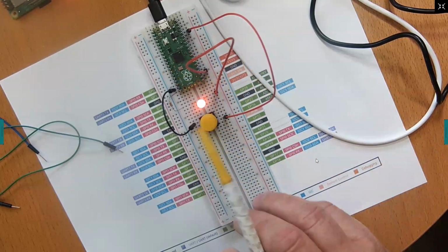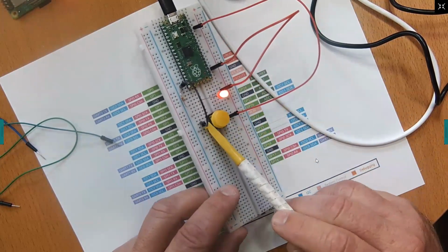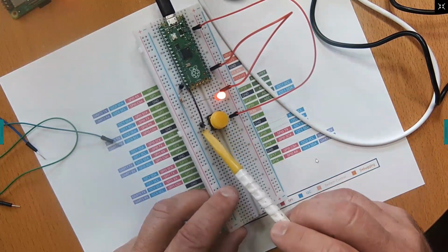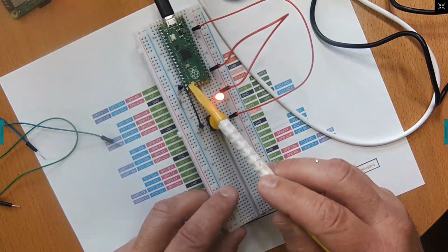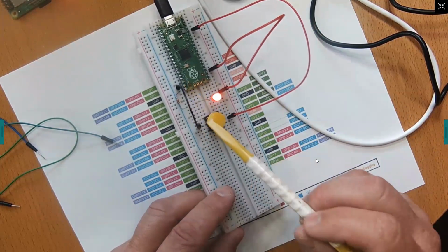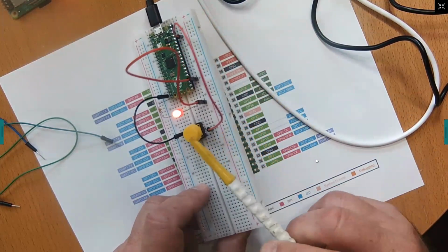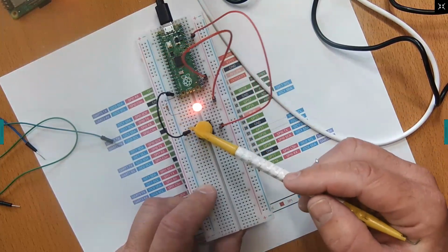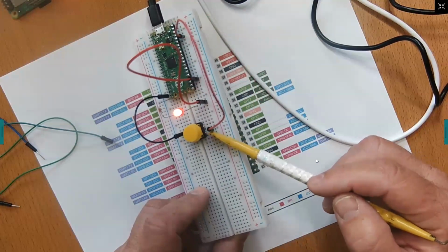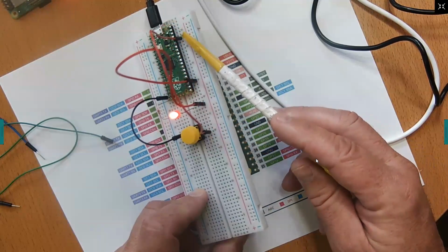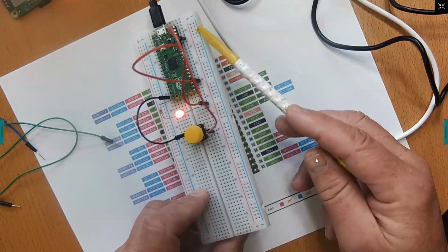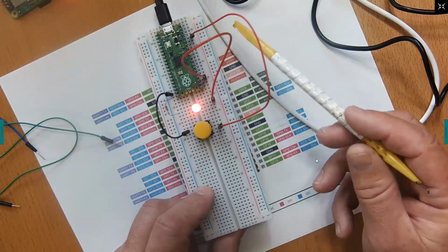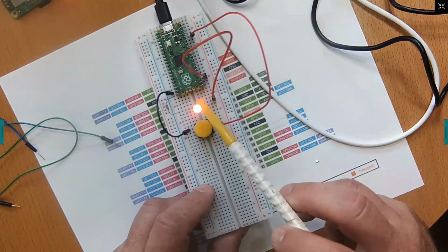For the button, on this side, I've got that first pin there connected to pin 14, which is the second pin on the Pico here. And then on this side, I've got the opposite pin, the pin diagonal across the button there, connected to my 3V3 power, which is number 5, I believe, up here, the 5th spot. 1, 2, 3, 4, 5. Okay, so that's how I've got it wired currently.